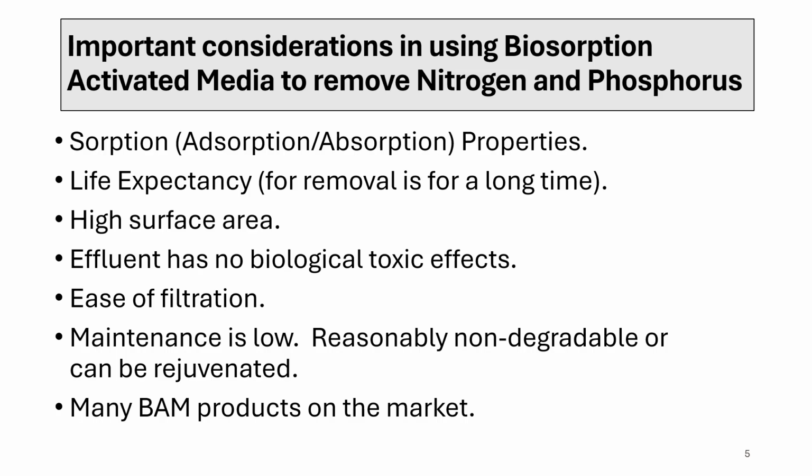Life expectancy is another critical consideration. You want a media that will continue performing its removal function over a long period of time, making it a worthwhile investment. Closely related to this is surface area, since a high surface area allows for greater contact between the water and the media, which improves overall treatment efficiency.